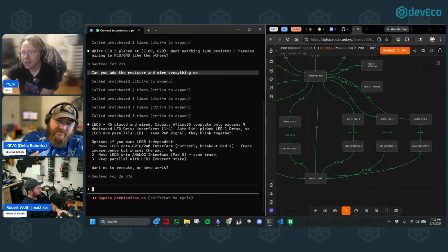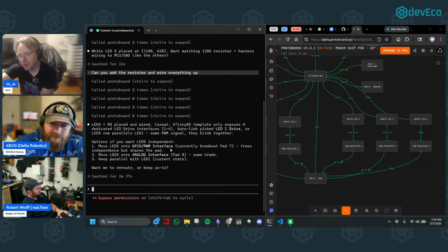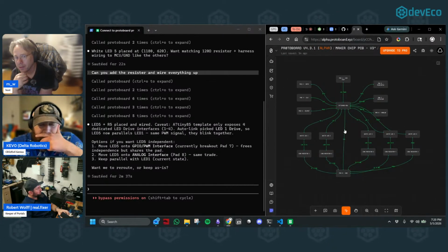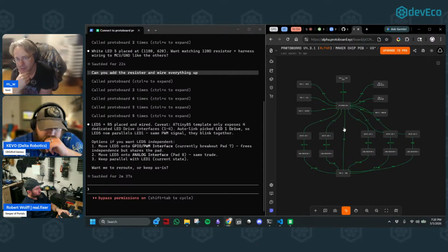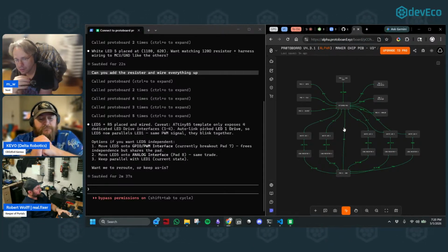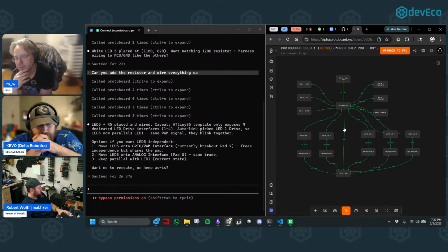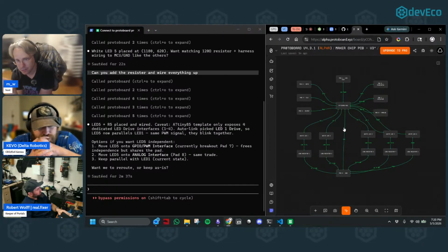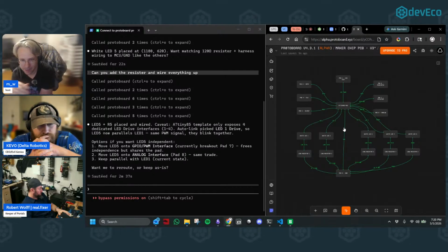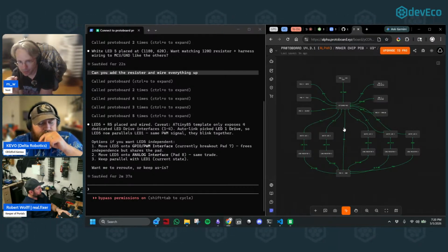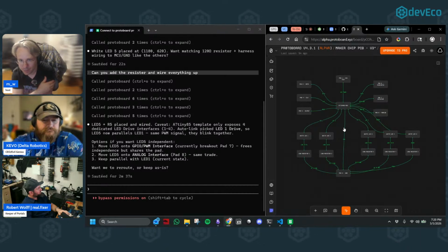But I think that you'd probably want to consider different topologies depending on how many you wanted to add. To consider Charlieplexing or serial LEDs. That makes it much easier. You could use this tiny and drive hundreds of LEDs if they are using the NeoPixel style. Those are a little taller though, so you'd have to check if they beat your constraints.